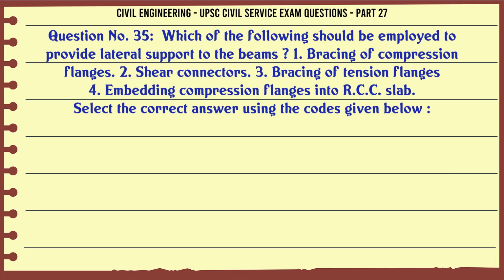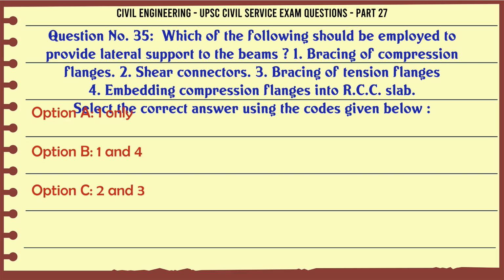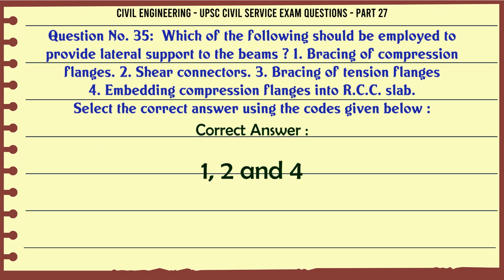Which of the following should be employed to provide lateral support to the beams? 1. Bracing of compression flanges. 2. Shear connectors. 3. Bracing of tension flanges. 4. Embedding compression flanges into R.C.C. slab. Select the correct answer using the codes given below. A. 1 only, B. 1 and 4, C. 2 and 3, D. 1, 2 and 4. The correct answer is 1, 2 and 4.